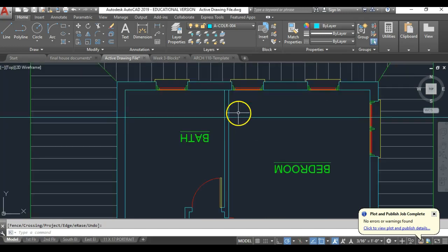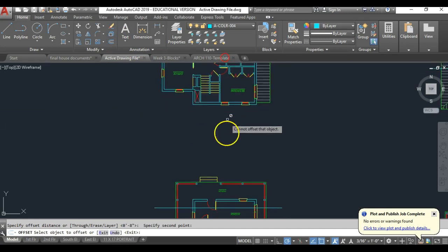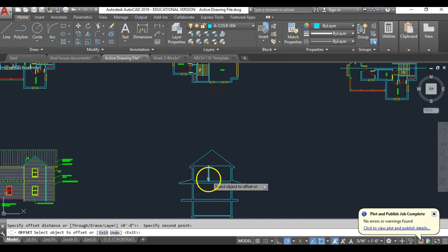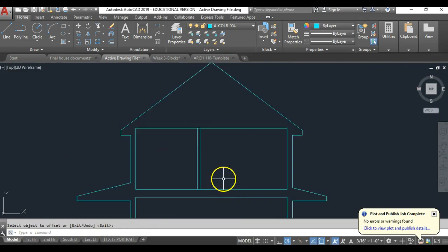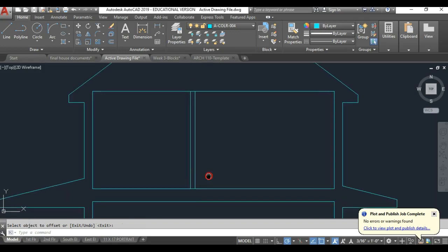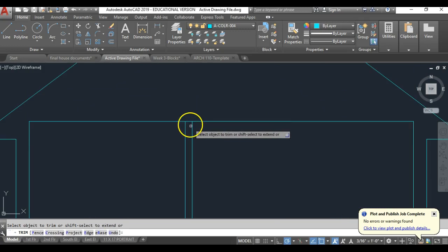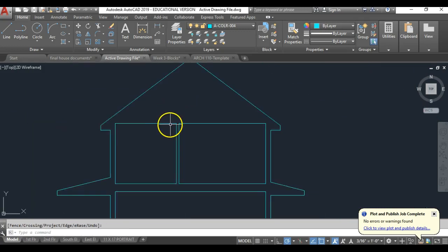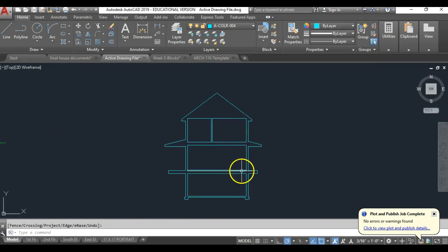If you don't remember the thickness, you can go up here and just hit offset and say offset from that side to that side, or I could have copied it and already have been done actually, but I have to go down here and offset from here to here and hit enter, and I'm going to trim up the zones in between here. So I'm going to do it short with my TR shortcut command. You guys can start figuring that stuff out, and I've got all my walls drawn. So I'm going to end this video here, and we'll come back for some extra details and follow-up videos.